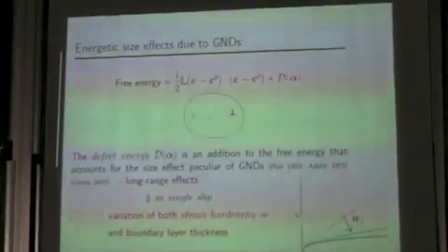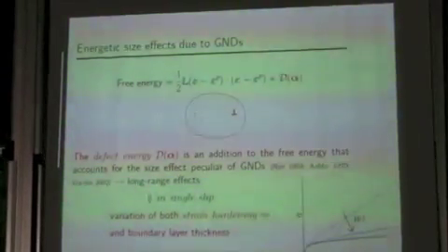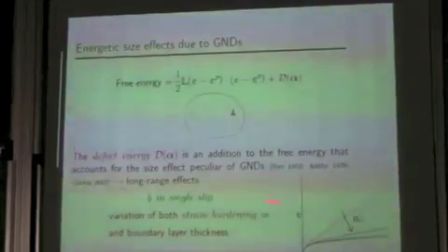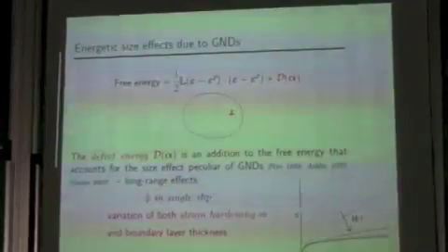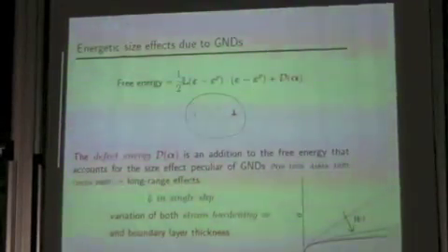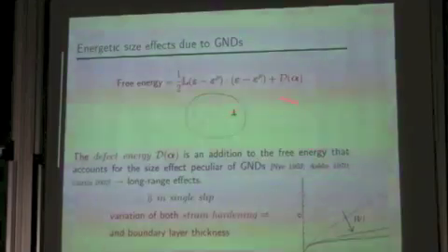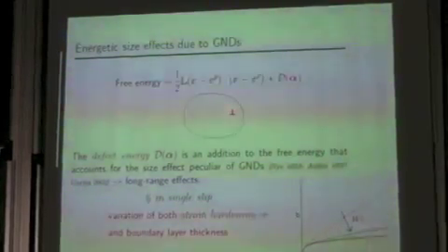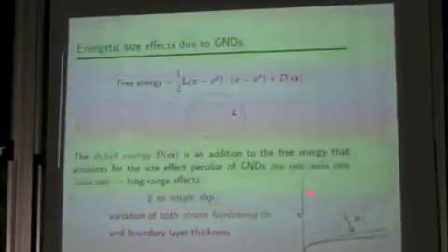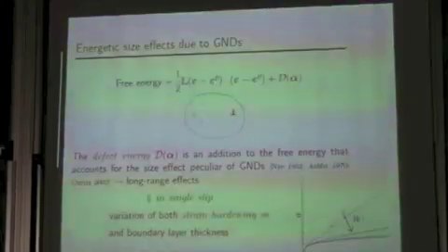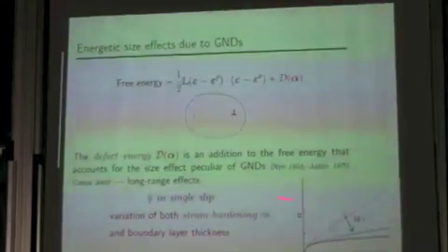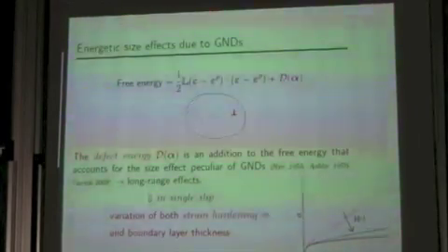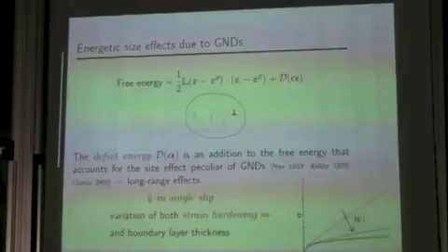And this ingredient in higher order or conjugate gradient plasticity is expected to provide just strain hardening variation accompanied with diminishing size effect, if at least the defect energy is quadratic in Nye's tensor, otherwise we have different effects. I just wrote that this is true in single slip, but if there is multi-slip,